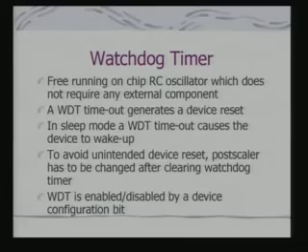We shall not have time to go into details, but one of the bits in that register is for enabling or disabling the watchdog timer. If I disable the watchdog timer, then all these things are of no consequence.